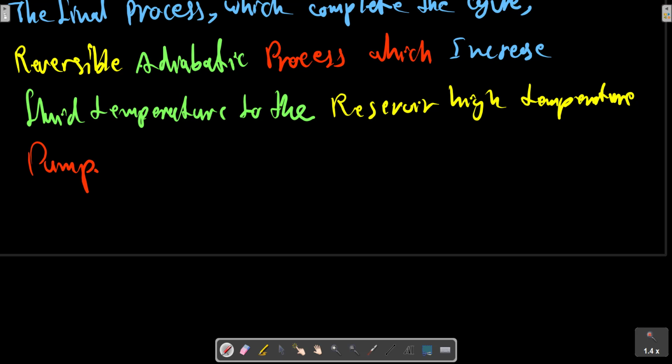If this were to be done with water as the working fluid, a mixture of liquid and vapor would have to be taken from the condenser to the compressor. This would be very inconvenient in practice, and therefore in all power plants the working fluid is completely condensed in the condenser, and the pump handles only the liquid phase. Since the Carnot heat engine cycle is reversible, every process could be reversed, in which case it would become a refrigerator.